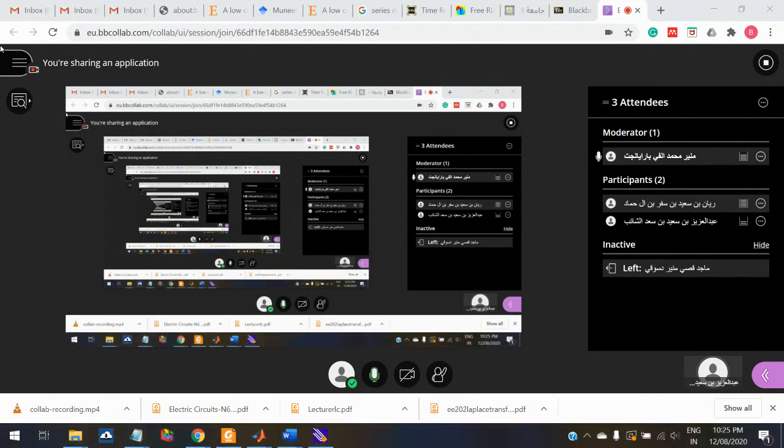So there are two roots. One root is very close to 0, and that guy will make the system overdamped. That means it will not prevent the system from going slow. It will always have a high time constant, so it will respond very, very slowly. You understood? That's the meaning. Yes, sir. Inshallah, we will continue our discussion because we have a lot of cases.